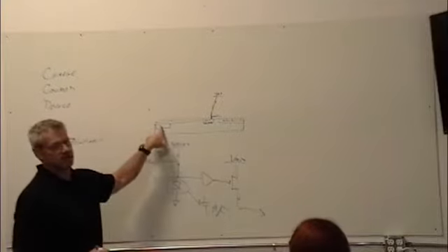So let's say this is 99% efficient. Woo, 99%. That seems like a really big number. That seems really good, right? Until you get to the other end of the line. 99% of 99 is 98%, and now you're at 96, I think, and then 93, and then 92, and then 80 some odd. I mean, just start multiplying by 0.99 each time. And you rapidly come out the other end with, you wanted resolution and you've got it, but you've got no signal left.